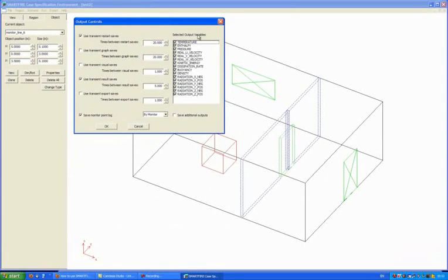In the right-hand panel we see the list of output variables which can be saved based on the module activations. Whenever you change the module activations, this list will change and you need to select all of the field variables you actually want to save. In this case, I'm happy with all of the options that were set, so I don't need to change anything.